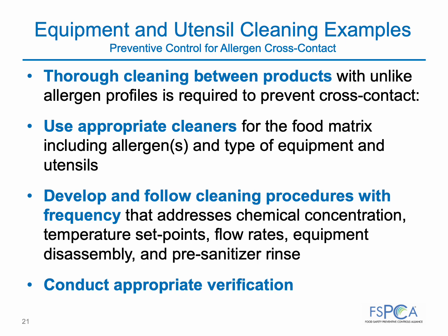FARRP has published guidance on components of an effective allergen control plan, which also describes recommendations for allergen cleaning. Cleaners must be effective at removing the type of soil and appropriate for the specific equipment surface. Cleaning activities must follow sanitation SOPs and be consistent with the instructions on the cleaning product's label. The SOPs should include detailed instructions to ensure that the personnel who are cleaning know what steps are required.